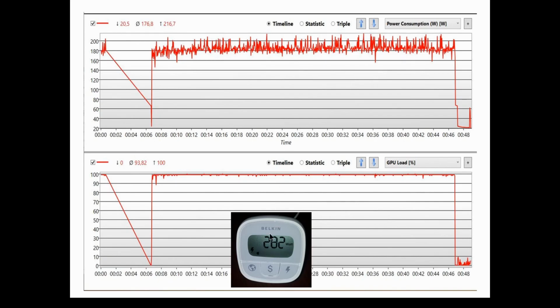Now, this down at the bottom is a measurement of the total watt consumption of my entire computer at this time, and it's 280 watts, all right? So my GPU is 180 watts, and the total computer is 280 watts. So there's 100 watts missing here. You would think it'd be 250 watts and only 30 watts, but no, there's 180 watts and another 100 watts missing. This reflects what the CPU is using, and I recall that was around 30 watts, what the motherboard is using, losses in the power supply, usage by the power supply. All of those other things add up to about 100 watts.